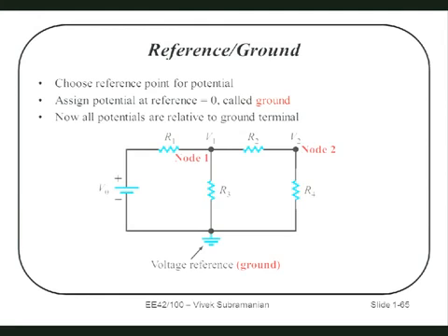So the ground doesn't necessarily have to be at that node, does it? No, you do not have to place ground here. You could choose, just because you want to do it that way, to place the ground up here. That would be fine. You can place it anywhere. It just means all your equations have to be written accordingly. If you decide to put a 0 into your equation for some reason to represent a voltage, remember the 0 is that point. It's easier to put 0 here for two reasons. One, it's close to the negative of the battery, which means the battery voltage, let's say this was a 9-volt battery, then 9 means 9. 9 doesn't mean something else. So it just makes life easy. That's why we do it that way.